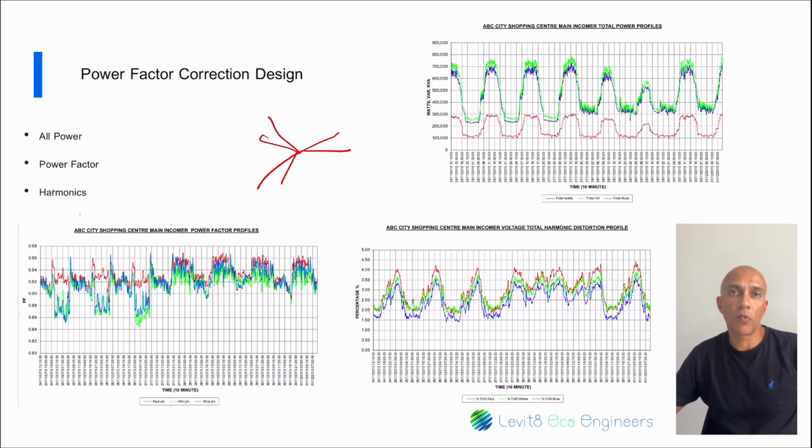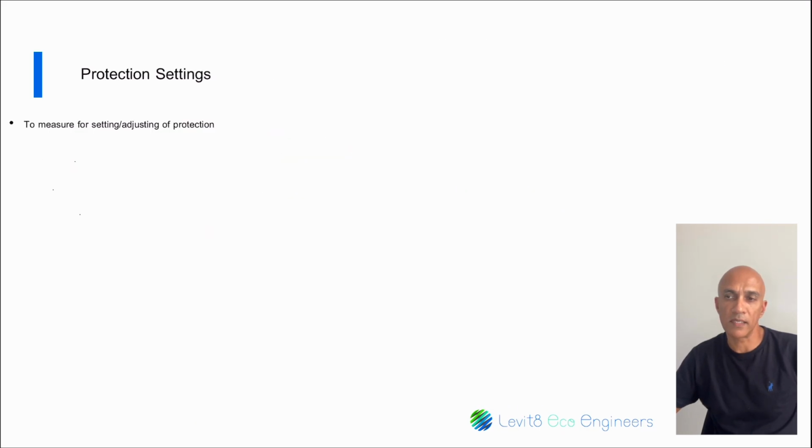Measurements may also be required for very sensitive investigation work, such as for determining protection systems on MV settings. So in order to do that, you would have to measure. You would have to know the dynamics of operation of the system being supplied by the feeder and protected.